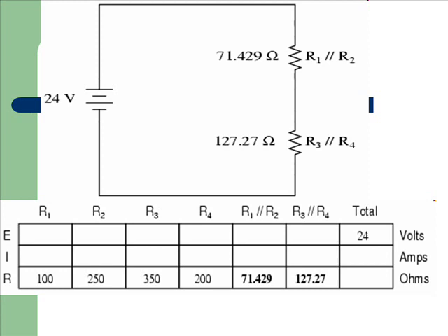In the example circuit above, R1 and R2 are connected in a simple parallel arrangement, as are R3 and R4, having been identified. These sections need to be converted into equivalent single resistors, and the circuit redrawn. The double slash symbols represent parallel, to show that the equivalent resistor values were calculated using the 1/(1/R) formula.